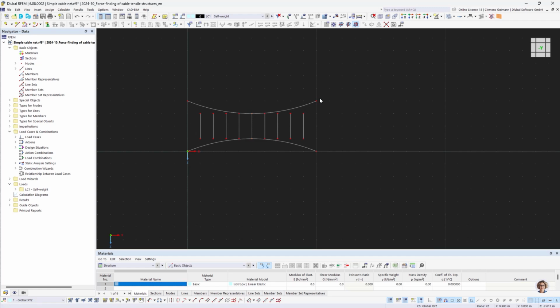And I want to connect those straight lines now to the arcs, and there's a quite handy way to do this. There's an option that has not been available in the software for too long, and that is the extend graphically command. There's the opposite command as well, the trim graphically. It does the same, but the other way around.